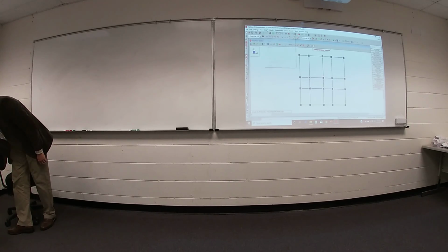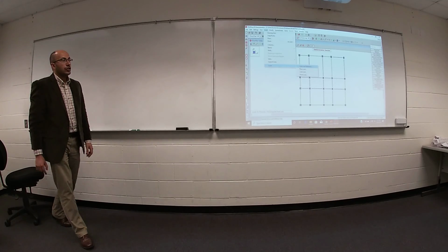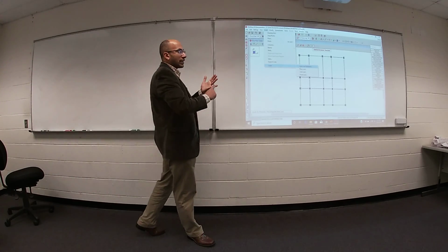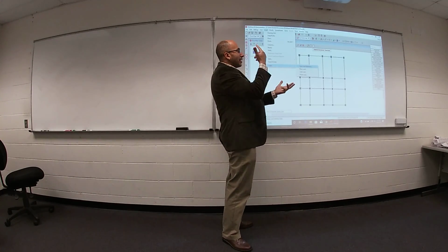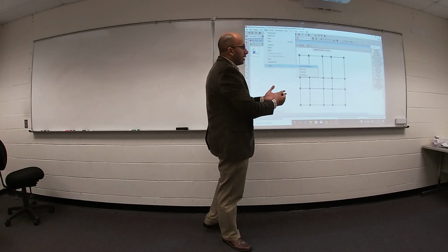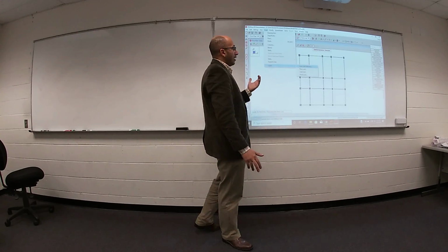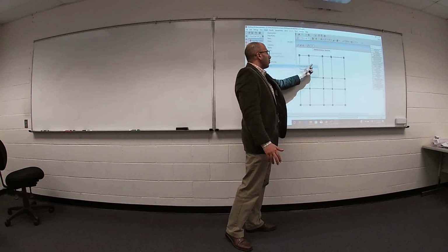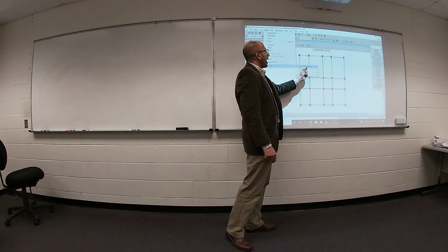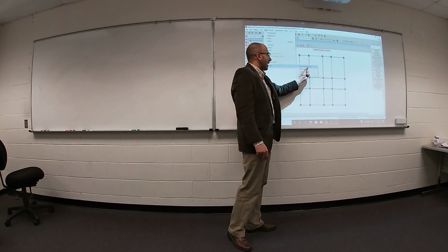If you would like, insert loads. This one. You can define. You can put your name. What is the value of this live load? And you can define everything. Once you define your load with a name, go ahead and check area load. You will find